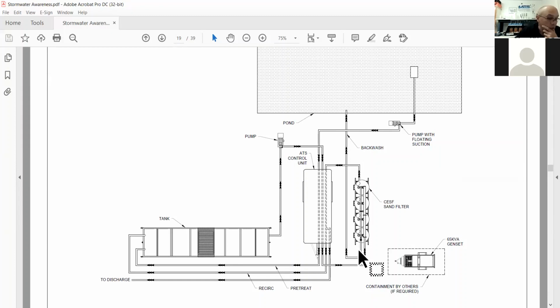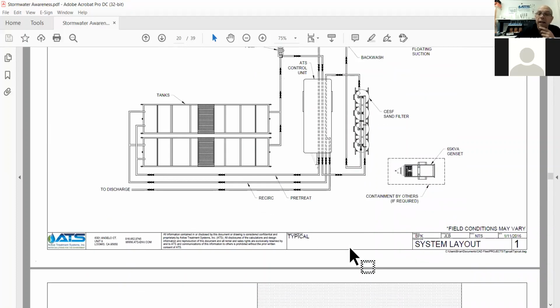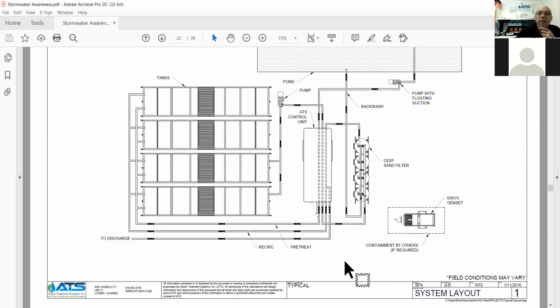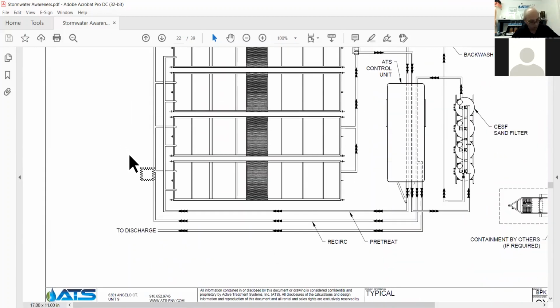For each additional 200 gallons per minute added, expect about 400 more square feet in the shape of a 40-foot by 10-foot tank. So again, the only thing that changed here is one tank and another tank for 800 gallons. These constraints will follow suit up to about 800 gallons per minute, and at times can squeak by 1,000 gallons per minute. When the systems are larger than 1,000 gallons per minute or are multi-year operations, basins rather than tanks really start to make sense. So I am going to break this back to 100% as I move on.